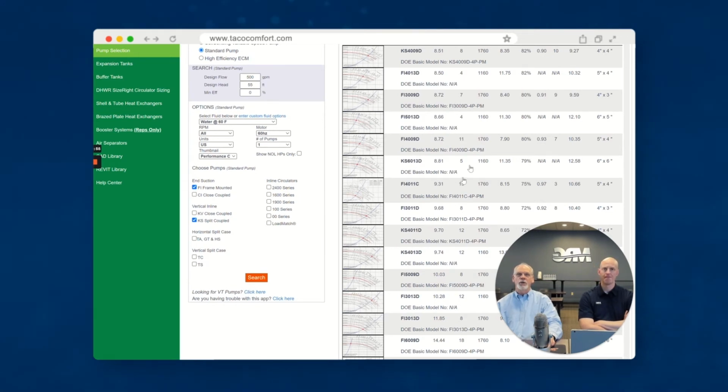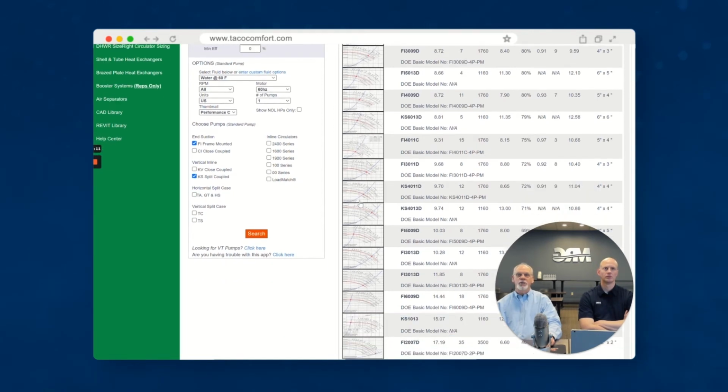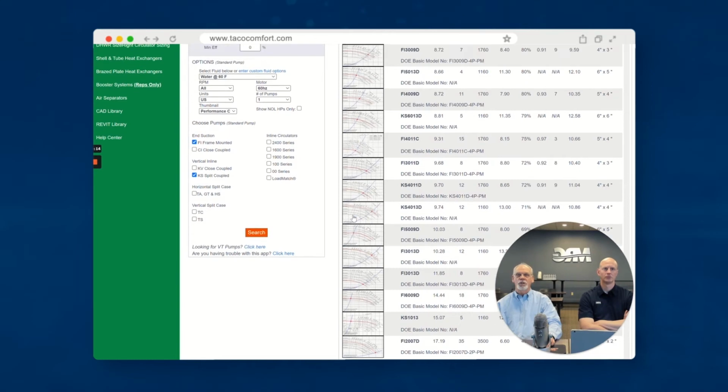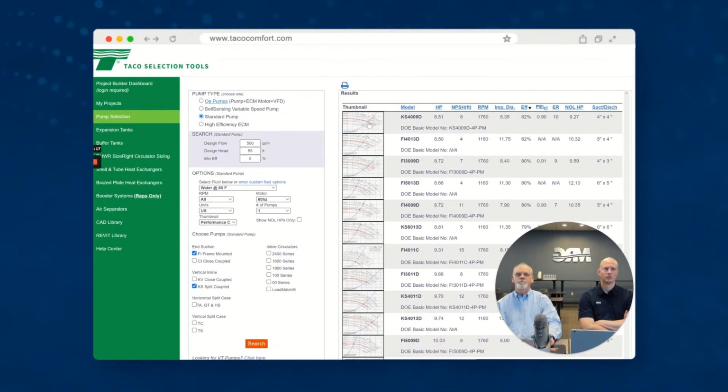Yeah. And as we look through here, we got a 4-foot net positive suction, but we also have one down here that is 18. All right. And it's way back on the curve too. So that's another thing that you don't like. But all these pumps will give you that GPM at that head based on what you have, but they're not all good selections. So they do list them by the efficiency first, and I look at the efficiencies plus where they are in the curve, plus what my pipe size is and my pump connection size to make sure that I've got enough pump to make this work economically with my horsepower of my pump. All right.